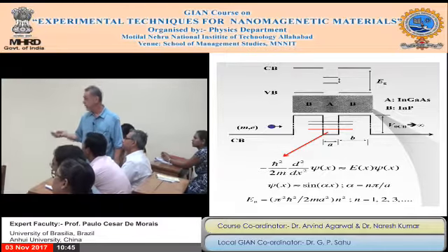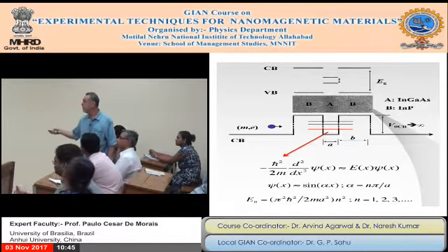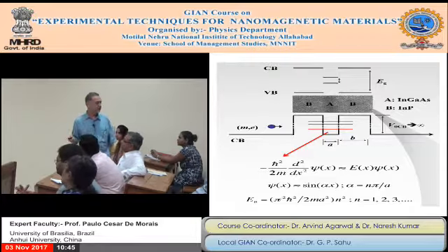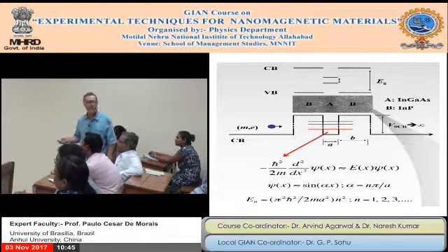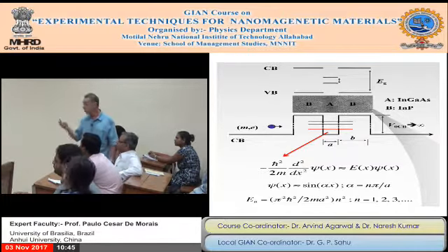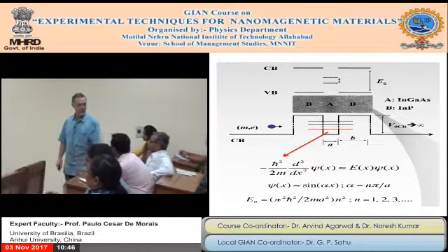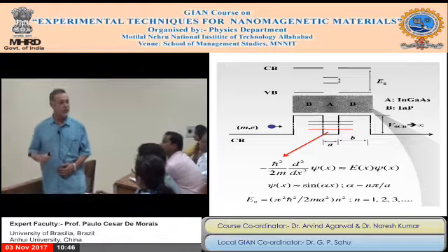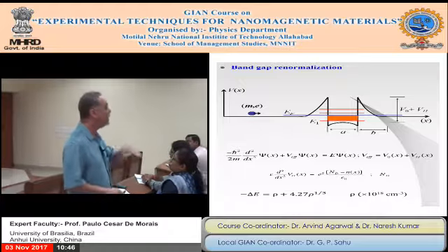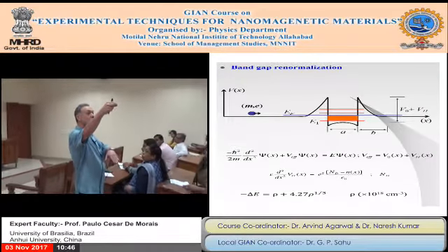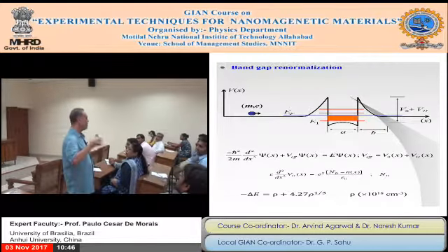So you can see here the band edge is flat, right? But if you take too many electrons inside, it is not flat anymore. It is like this. It bends. Why does it bend? Because this bend is a potential, electric potential. And if you take any charge near any potential, that charge just modifies the potential.